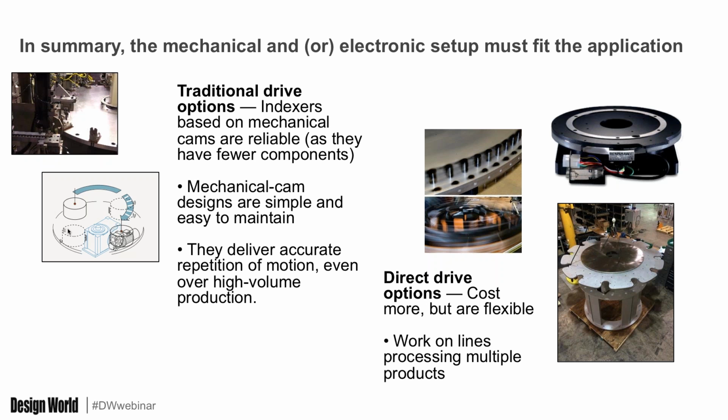But setups with direct drives and electronic camming excel where applications have lower inertia and need variable output. Electronic camming with traditional servo or even direct drive setups can have lower inertia, so they work with light or moderately heavy loads. They use servo motors, drives, and controls, and feedback devices. So all of those components cost money. It's something to keep in mind. But systems with electronic camming excel